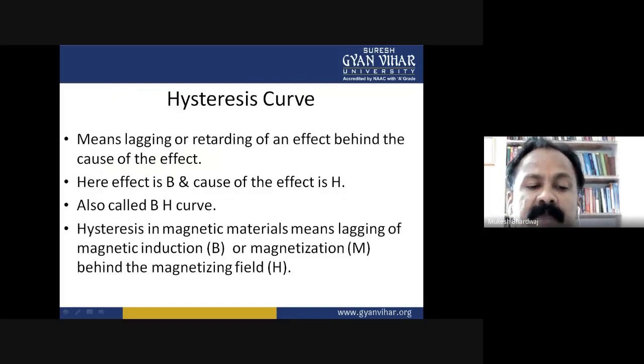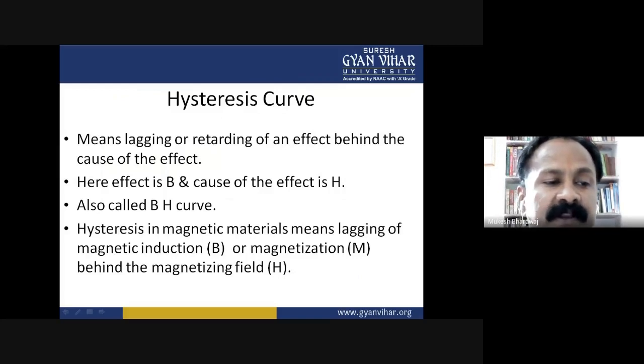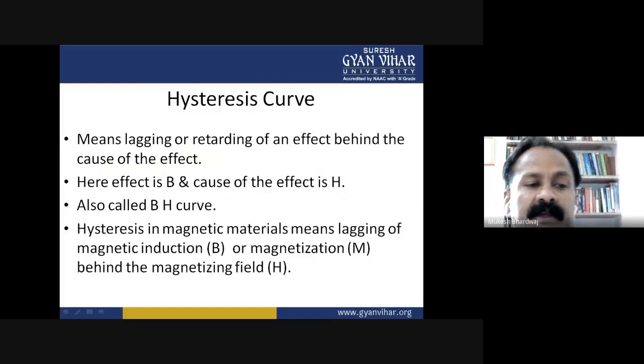In converse of the magnetostriction effect, the Villari effect is also observed in magnetic materials, where a longitudinal deformation leads to a change in permeability in the direction of applied strain. In general, a material which extends on magnetization will have its permeability raised by tensile strain, whereas for a negative lambda material, an externally applied pull reduces the permeability.